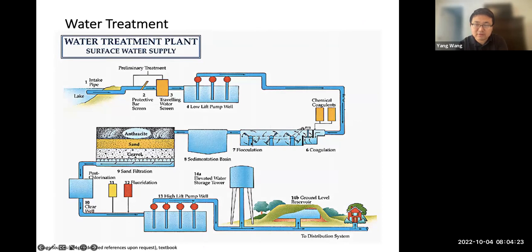Well, for the flocculator, for the flocculation, this is a process where we are forming these larger chunks of particles, forming these flocs. So under this situation, we would prefer a slower mixing, right? Compared to the coagulation, because here we still need some mixing because the coagulants might not be uniformly suspended here, right? We still have these blades here to stir the water, but without the fast speed to break down the flocs, right?